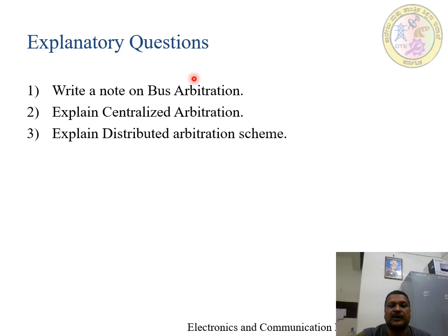There is centralized arbitration, which uses a series of signals to assign the bus mastership, and a distributed arbitration scheme, in which an identification number is assigned to devices and a pattern is generated on the arbitration line, compared, and the conflict is resolved.